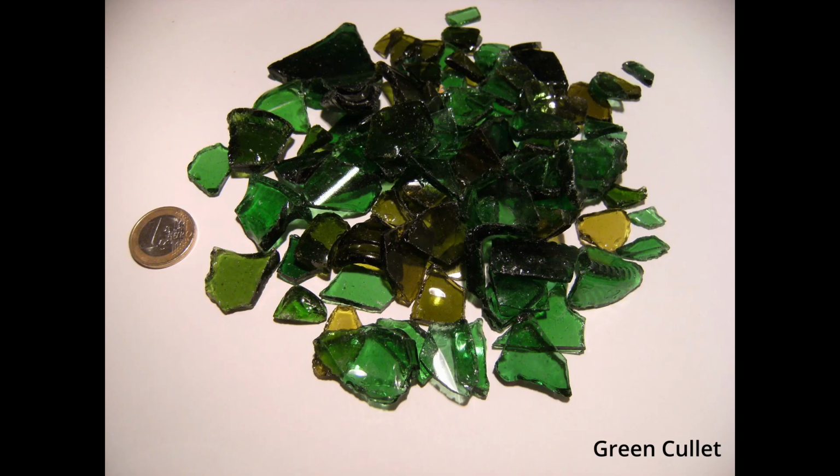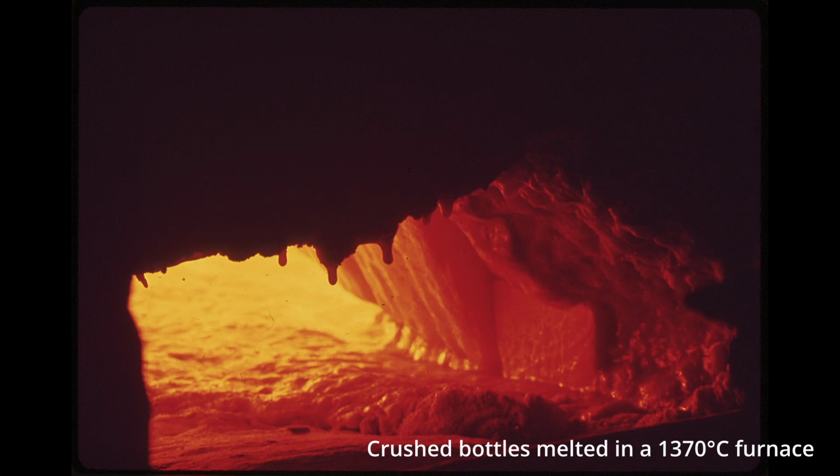To manufacture glass, the raw materials are ground together into a powder and then mixed with crushed recycled glass known as cullet to reduce the energy consumption during melting. While raw materials and cullet melt at the same temperature, cullet's prior chemical reactions eliminate the need for extensive energy use in subsequent remelting, requiring only enough energy to reach a molten state.